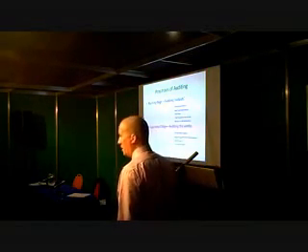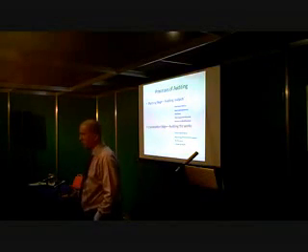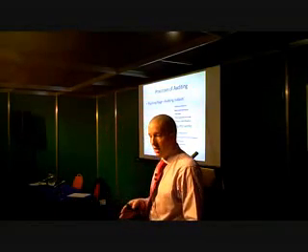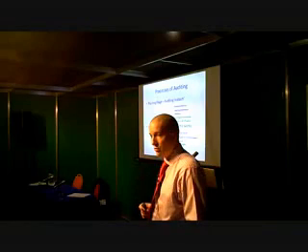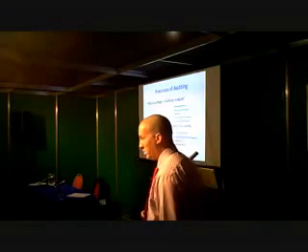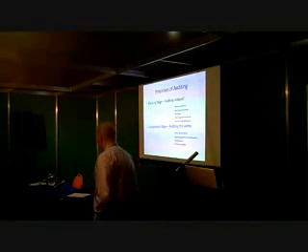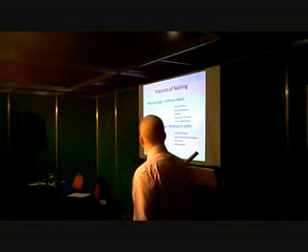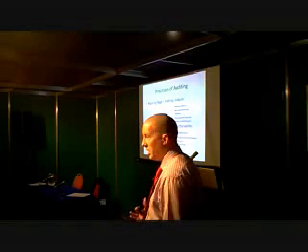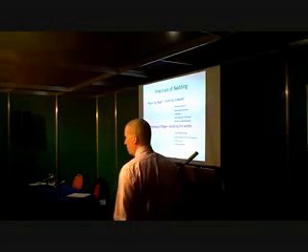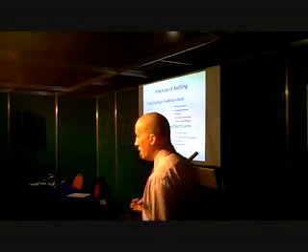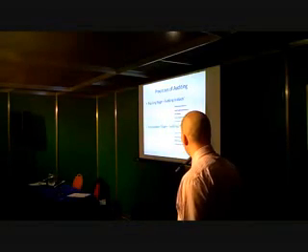But following on from that, reporting the non-conformances, rectifying those non-conformances, and then follow-up audits to ensure that what you've requested to be done has actually taken place and is now safe for the road worker and the road user, are going to be important elements of the construction stage audit. So, those are the processes for auditing. As I said, the construction stage is where, I view, the industry needs a lot of work. It's not up to the standard that we could expect, and you've only got to drive around and see the standard of traffic management yourselves to understand that isn't the case.